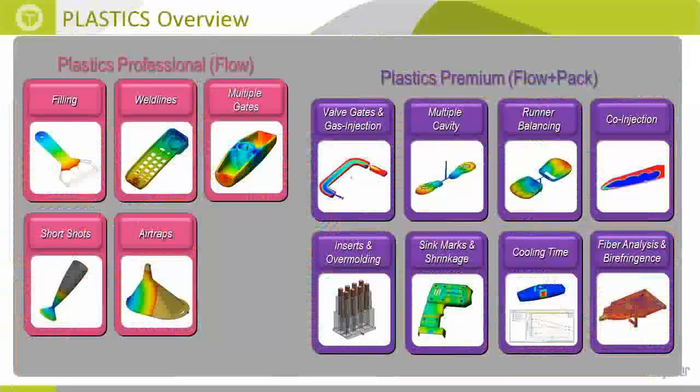We actually now in 2014 have a product that goes beyond these two modules for consideration of warpage as well. So Plastics Professional is really geared towards the designer. If you're the designer, meaning you're the one designing the part, you're not necessarily creating the mold, but some of these things, like short shots and looking at the filling process, is my mold, is this product I'm designing even moldable, are some of the questions that the designer needs to know up front before they toss it over the fence to the mold maker.